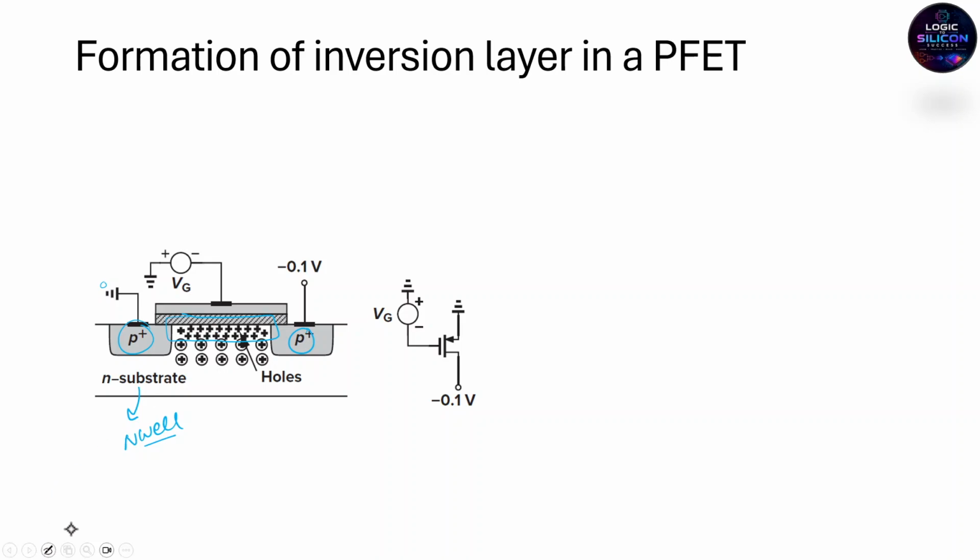That is the threshold voltage of a PMOS device, where this inversion happens. That's why for PMOS devices, VTH is generally negative, because we apply the gate voltage negatively. And that's why in numericals we always take the modulus of VTH. That is the whole reason for this VTH.